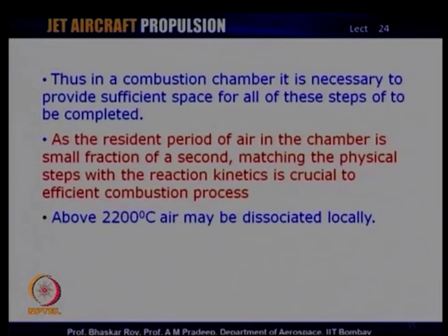It is necessary that sufficient space is provided for all the steps. We saw a number of steps. There was atomization, there was combustion, there is a creation of combustion products, there is a flame zone. You have to give the flame a certain amount of space to exist, and then the mixing of the combustion products, and then finally delivering it to the turbine. So, there are so many things to be done inside the combustion chamber very carefully, so that the combustion process is complete in all senses of the word. Now, this needs to be done in a very small space. However, that space needs to be sufficient for doing all these things in a step by step manner.